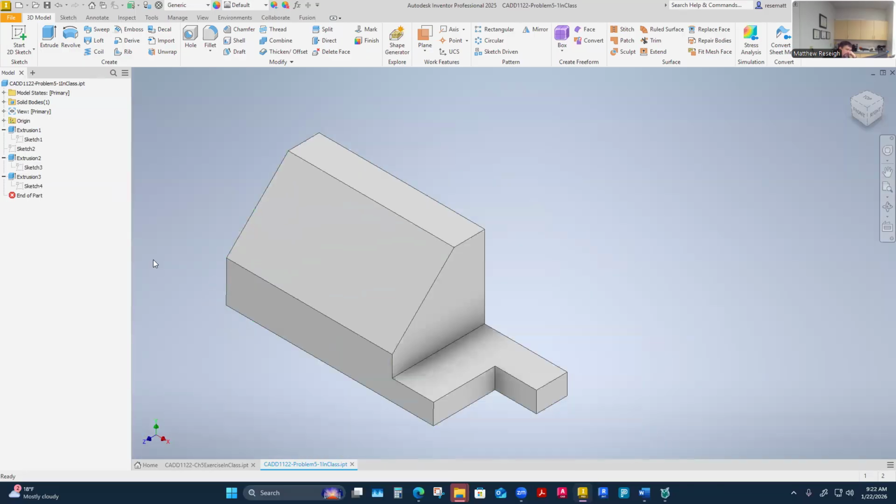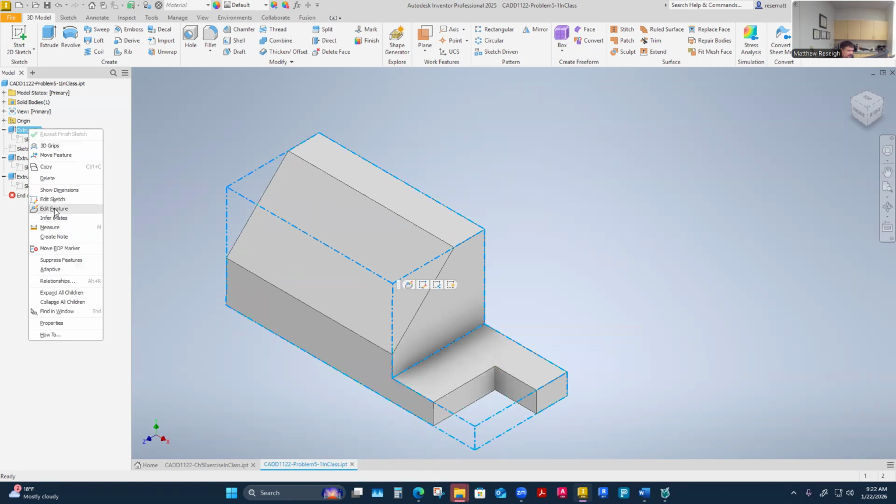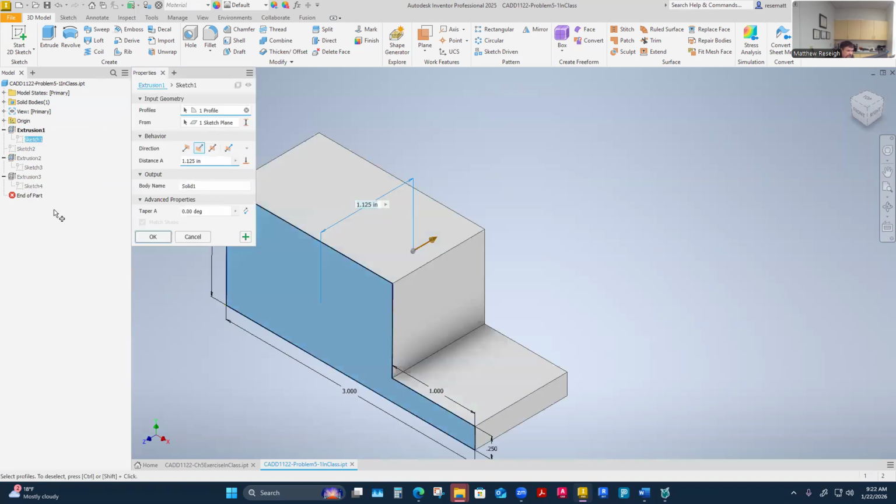When I mean blow up, it'll be like the extrusion will have an error with it, and maybe has an exclamation point or something. And if that extrusion has an error, then these extrusions are probably all going to have an error as well. So you'll just kind of have a domino effect if that's what I call blows up on you. And you have to go in now potentially. So every sketch that you change, there is a potential that you may have to go in and edit the feature and kind of repick the profile potentially. Maybe it lost its profile and it doesn't know where it is.